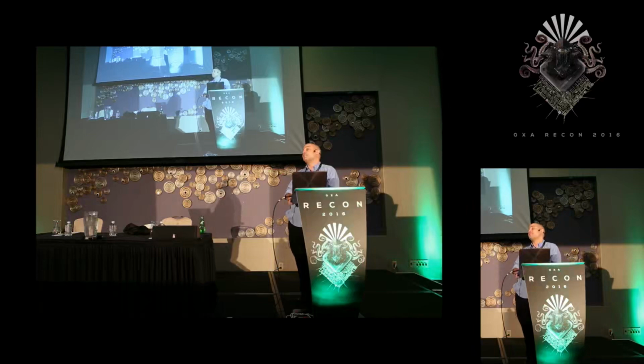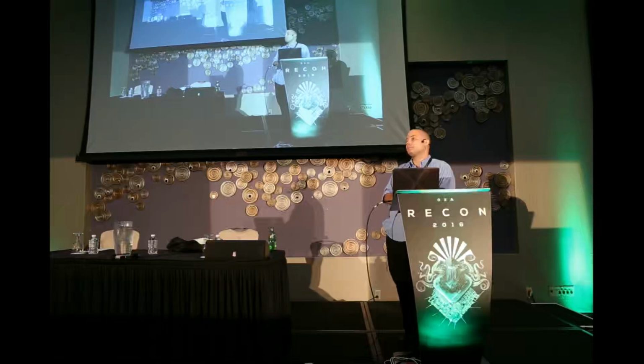The dead addresses actually didn't cause me any problem because when I was studying the software, I could see that they would read specifically from address 0, 1, 2, skip a byte, 4, 5, 6, 7. So this looked very unusual and tipped me off that there was something going on there. And then at the point when I actually had access to talk inside of the chip, then I could poke around a little bit. But no, when those dead spots are hit, there's no bad reaction. It just resets the chip, so I didn't lose any to that.